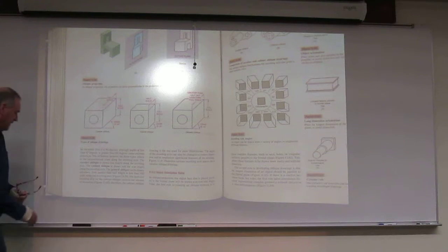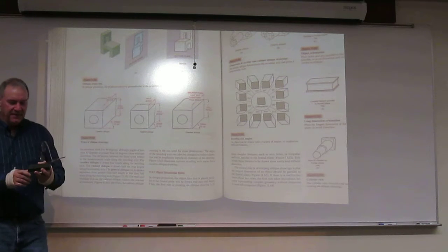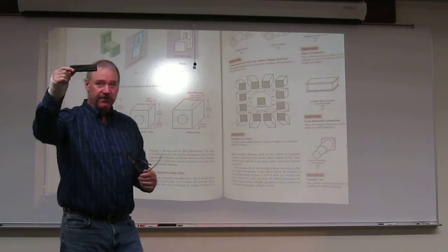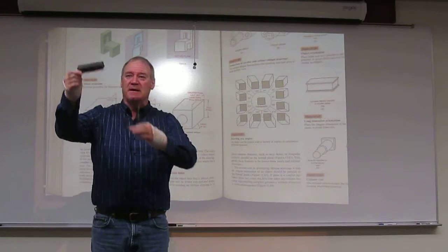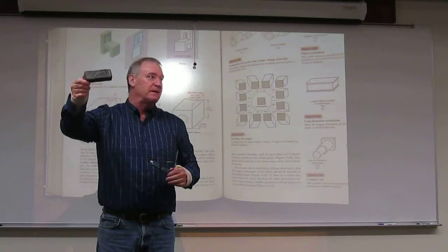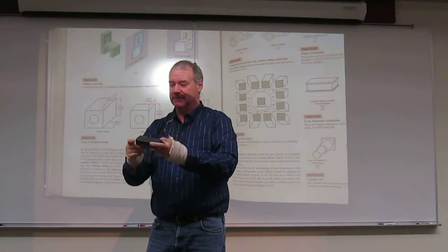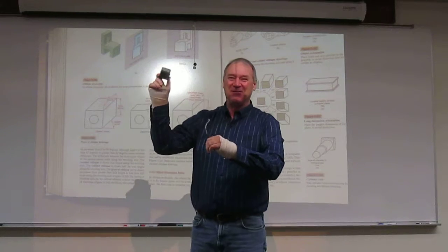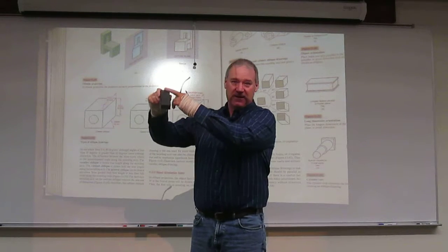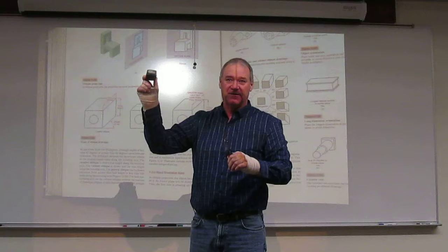If you looked at something like this, and I chose this for my front view, I don't have much of a receding axis. I'm probably doing a cavalier, full scale. If I chose this as my front view, I can't really hold on to anything. If I'm choosing this as my front view, now I've got a heck of a receding axis in proportion to the rest of the object.